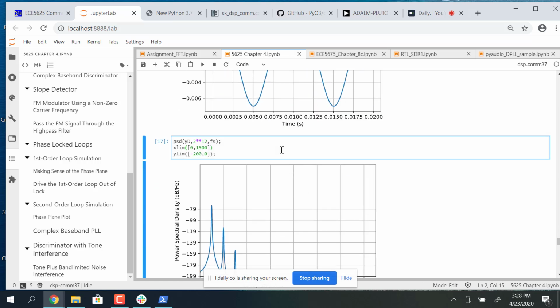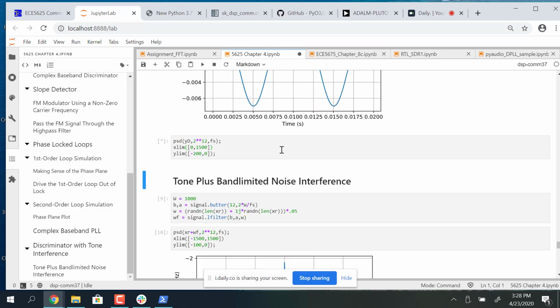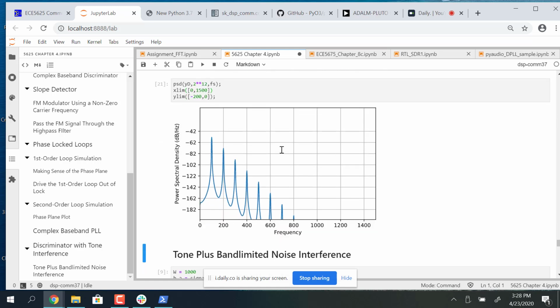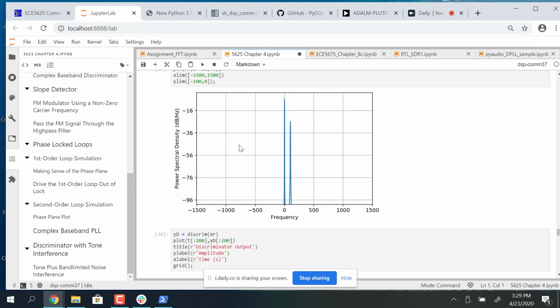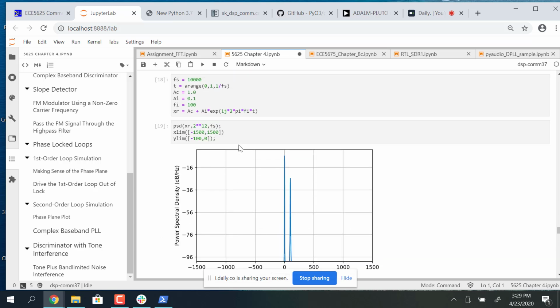And if I go look at the harmonic content, it's getting far worse. This is not our message, this is our interference, but the interference is just sort of taking over the discriminator at this point. And the information that would be on the modulated carrier, if I was to put that in here, would be getting swamped out and kind of getting destroyed by the interference.